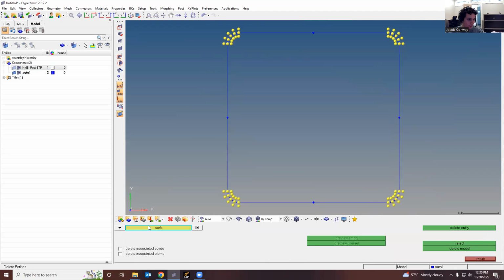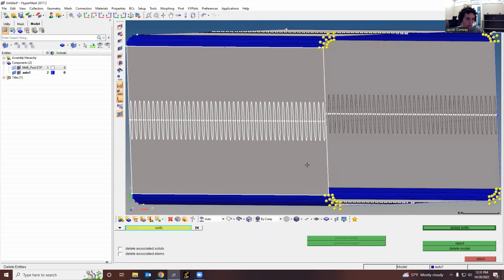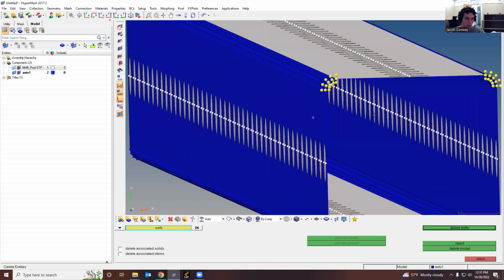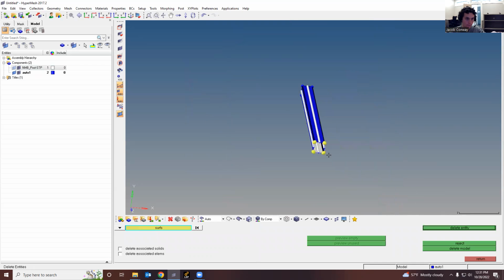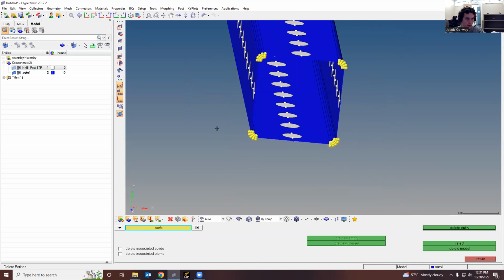So we're going to go here. We're going to go to this X tool. We want to have surfaces selected. And again, do that click drag on this area, just so we make sure we have all that selected, but then right click these four to make sure we don't cut those out, and then delete these entities.